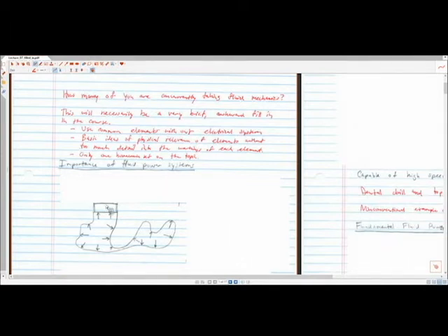I can very easily, in fluid power systems, distribute power. If I look at my electromechanical systems, if I want power delivered to a certain location, I have to run cables there, and then I have to have a motor or some sort of driving element at that location to apply power. Fluid power systems are nice in that they distribute power everywhere, in a sense. So if I push down on this piston, I can have some pretty irregular vessel, and it's going to create pressure everywhere normal to this wall. And what that allows me to do is actually use that for work.